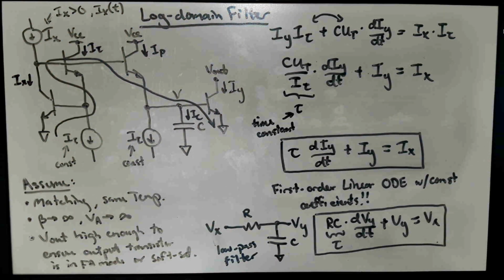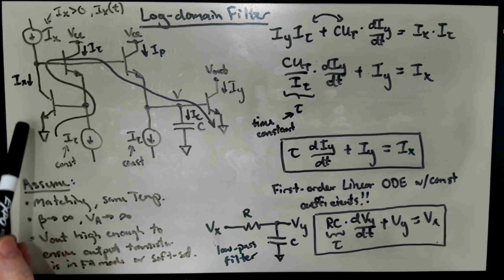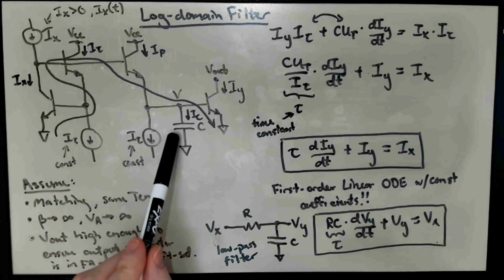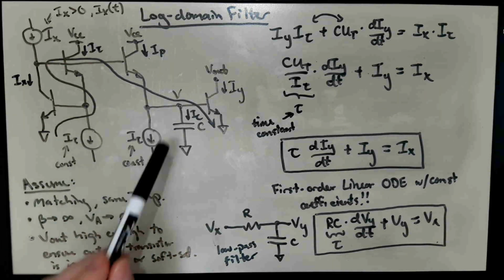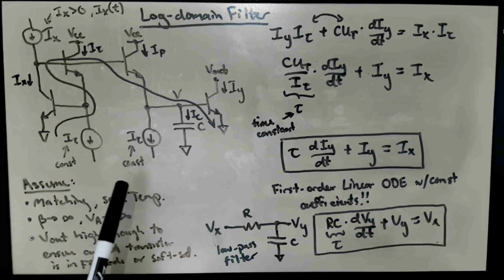This is not a fluke. These circuits can be systematically designed to be filters of arbitrary order. We can basically start out with a transfer function and systematically come up with effectively a translinear circuit with capacitors in strategic locations that basically embody that transfer function.